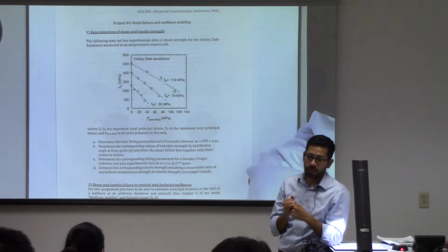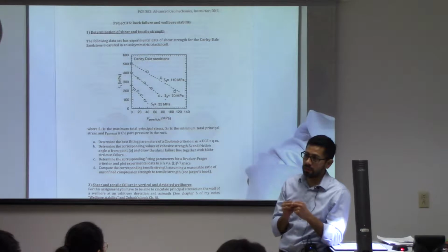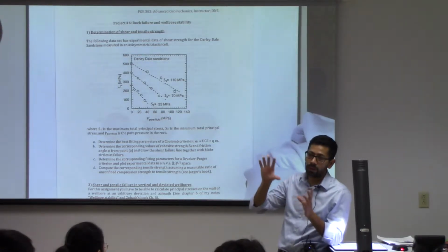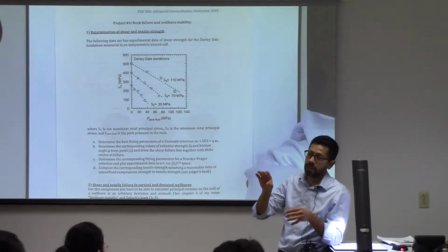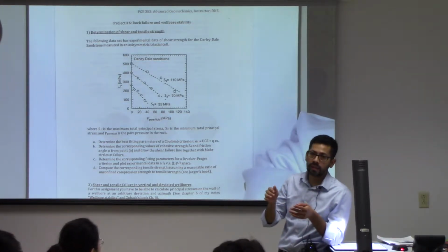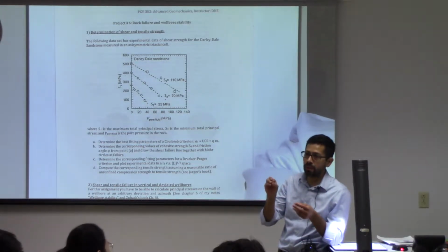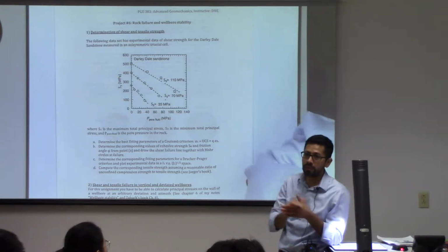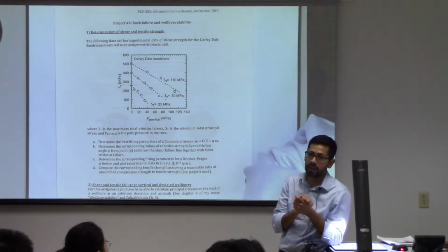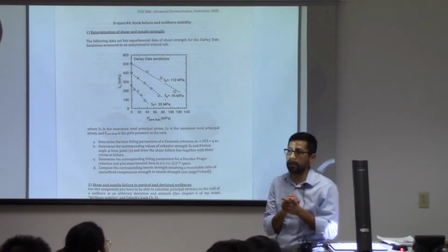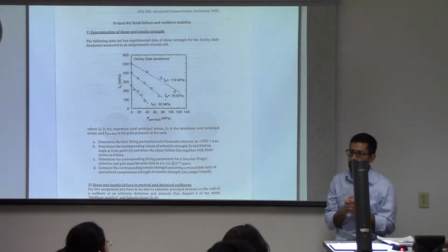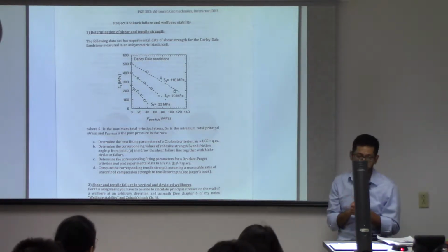We're going to use the equations of elasticity and the Kirsch equation, something that you have already used when we were computing stress around the wellbore. But before we were assuming that everything is elastic. Now we'll continue assuming that everything is elastic, but we're going to look for those points that exceed the stress delimited by one of these shear failure criteria or tensile strength failure criterion. And that's what we're going to discuss today, the tensile failure and the shear failure.